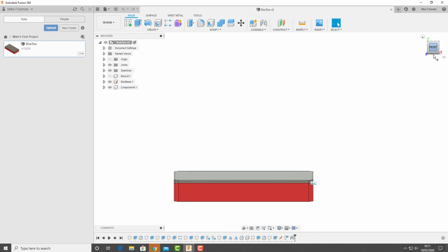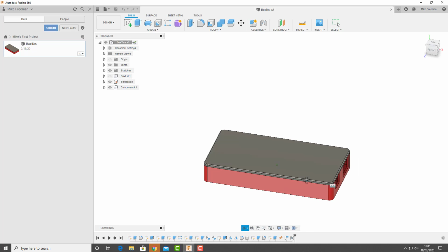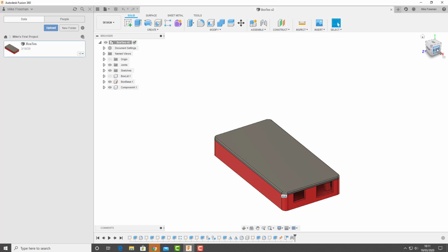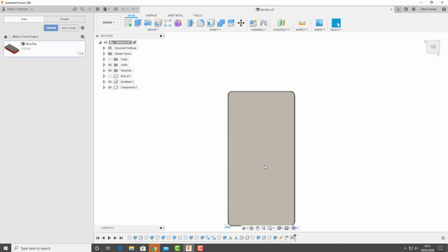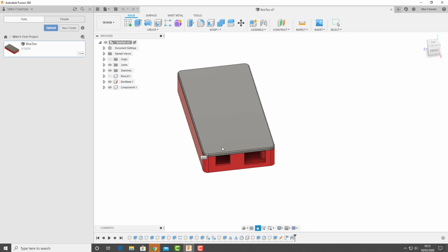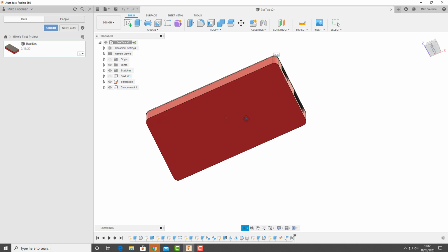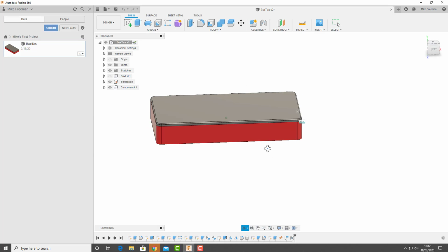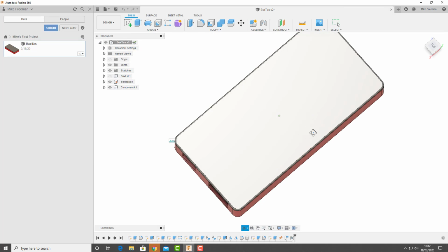For some reason you might think, well, that's the front view, but actually that's the side of my box, I want that to be the front. What you can do is go to the view you want, pull down here, and say set current view as front, and now it will change that around. But definitely, holding down that shift key and using that middle button to orbit, panning it out, and then pan across, that's your main view commands.